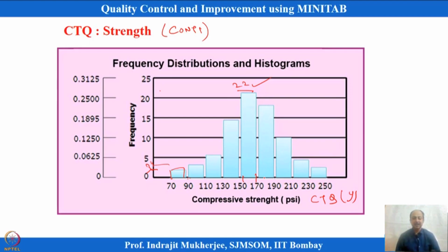From an engineering standpoint, yes, it is required, because you need to understand which specification is important and which CTQ is important, addressing the voice of the customer. That conversion happens at the design phase. If the design phase goes wrong, everything goes wrong. But when I have a strong design, I know the CTQs and then I have to improve them in the process. Then we see quality of conformance, which is the second phase of our discussion: quality of design and quality of conformance, whether we are adhering to the specification given by the designer for a specific CTQ.